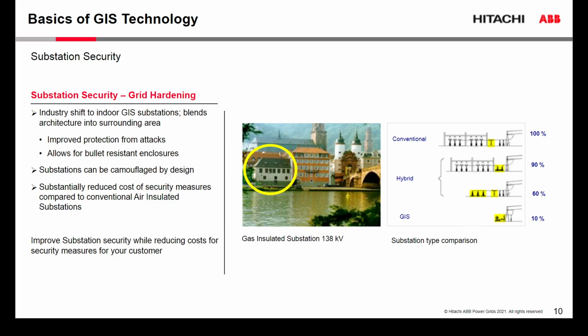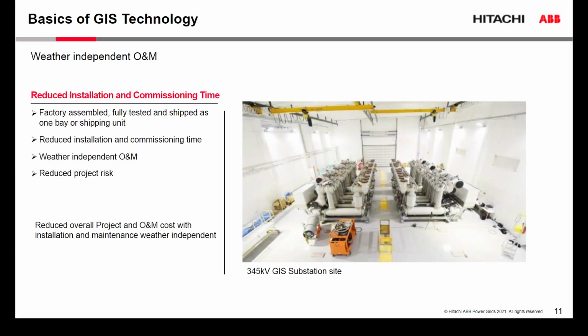And last but not least, to talk a little bit about the reliability. I mentioned reliability is a big aspect in today's operation of the grid, and outages are not welcome. And we saw that a couple of weeks ago happening in the area of Texas, where a cold snap created issues on substations, tripping breakers or creating, with icing of disconnect switches, situations where substations had to be interrupted.